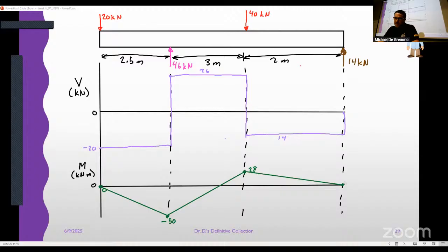And now you can tell me, okay, well, what's the bending moment at any point in this beam? We can figure it out. Right? I could say, hey, what's the distance away from the left-hand side at which our moment becomes 0? It would be this place, right? And so we would have to figure out where that is, but you know that it's got to be somewhere around the midpoint of the beam. And that's how we do it. And that's a simple point loading.